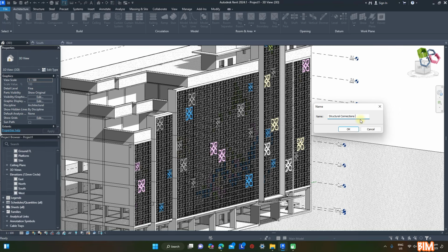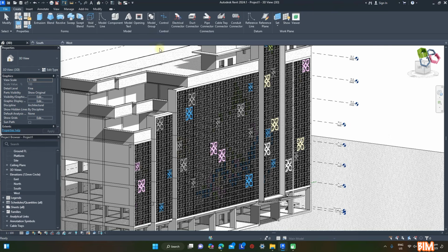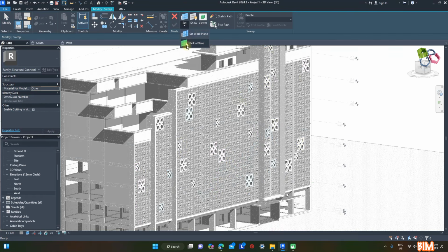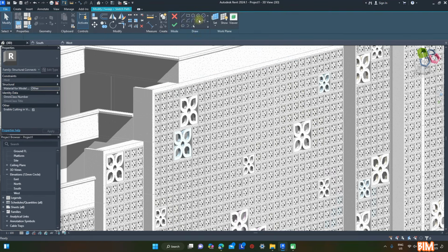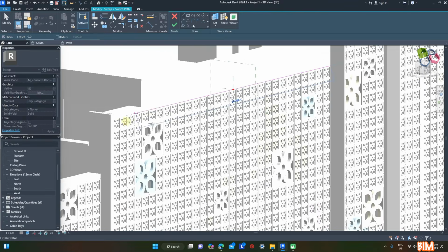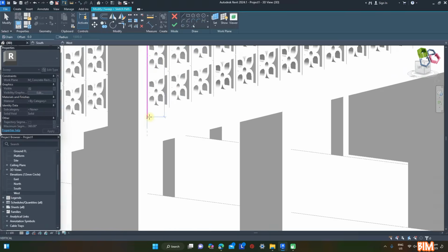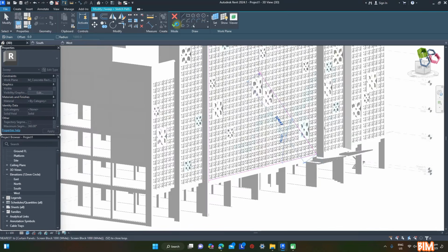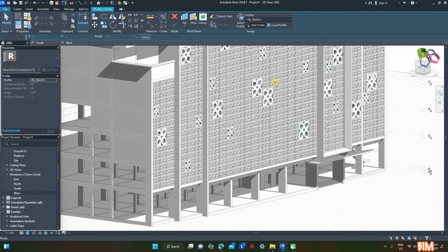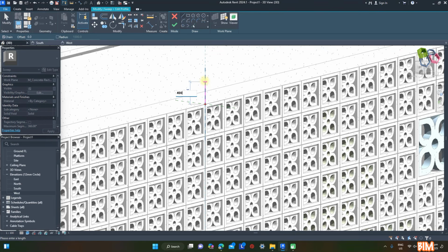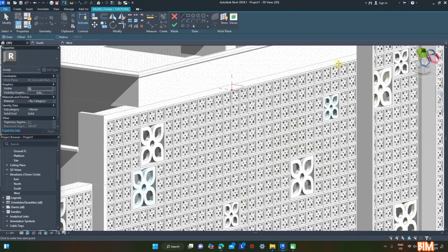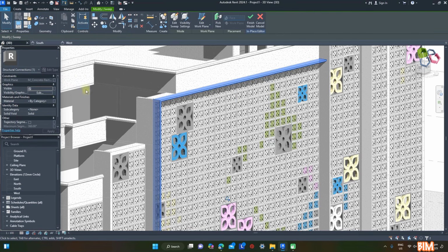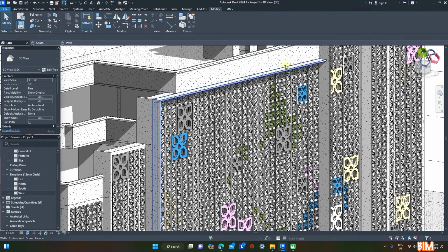For each model in place: name, category, set working plane. Prepare a path for the sweep. This time, the path should be 3 sides only, instead of 4. Draw a profile. This time the profile extrusion depth is reduced to give some visual effect. Profile size is reduced to 400 by 1000 mm. Assign the same material. Completed for the large panel.